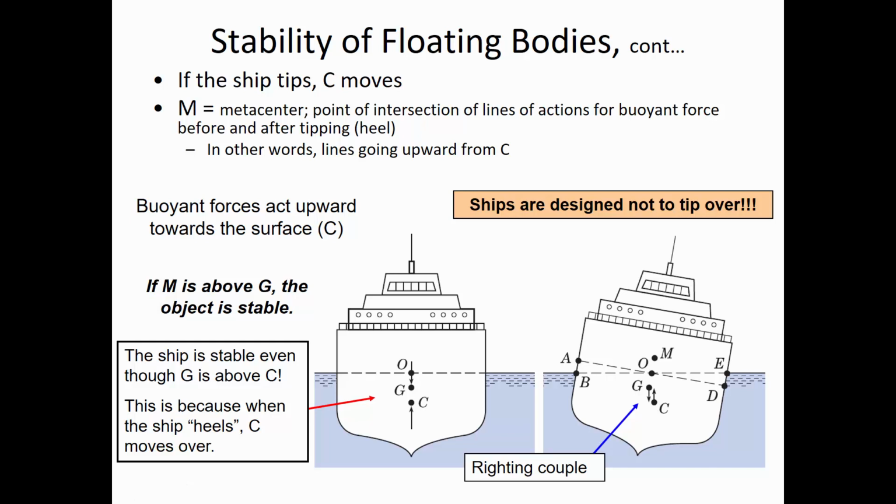So that's the water being displaced. G is dependent on mass. So if we load the ship with more and more cargo, what does that do to the metacenter if we are adding more mass? Indirectly it may, but the metacenter is unaffected by loading mass onto it. Loading the extra mass changed G. It changes the center of gravity. So the center of gravity is directly affected by the mass of the object. The metacenter is affected by the submerged volume.